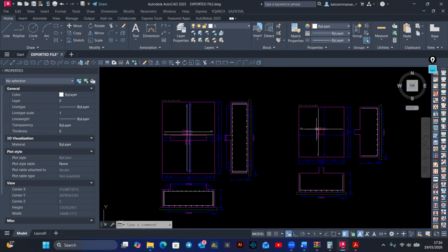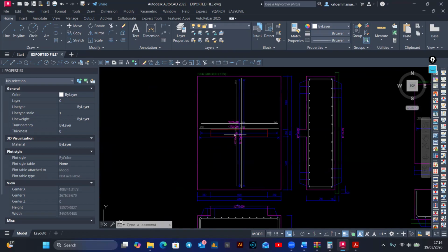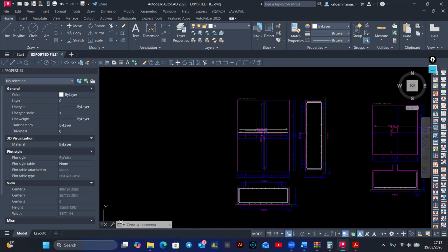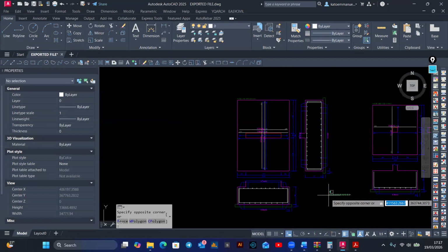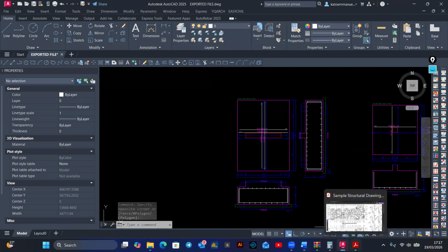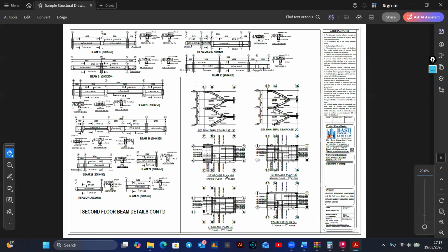Then the footing details, you need to panel beat them, because in these footings it's not necessary to have sections in either direction. It's just a section in one direction. You can cut off this, leave this, and then in your section details, you indicate that at that level you have a plinth beam.